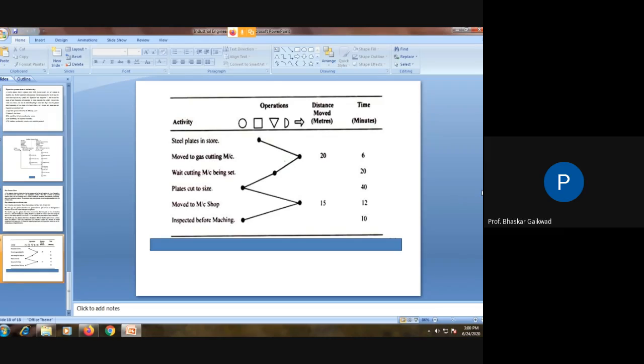After that, we'll go for inspection. Once inspection is over, then we'll send these jobs to the VMC machine. Again, transportation and VMC machine drilling will be there. There are operations. Sometimes from CNC to VMC, material may get delayed because whatever fixtures we have made on VMC are for 8 jobs, but 2 or 3 jobs are over from the CNC machines. For 2 or 3 jobs we cannot start our VMC, so we wait for 8 jobs to come from the CNC. Once 8 jobs come from the CNC, then we'll fit all these jobs.